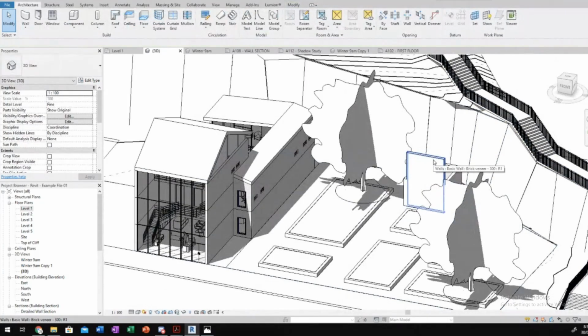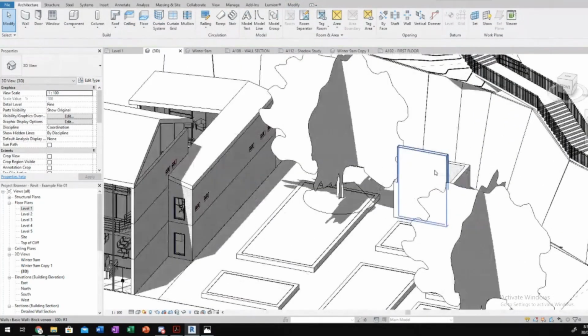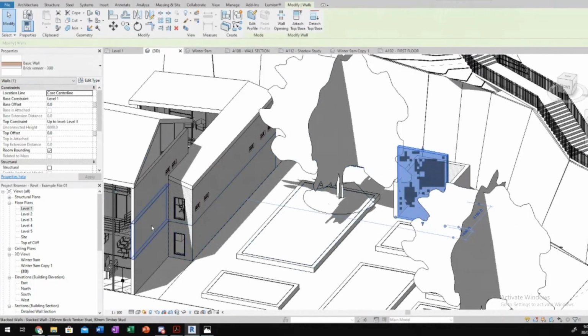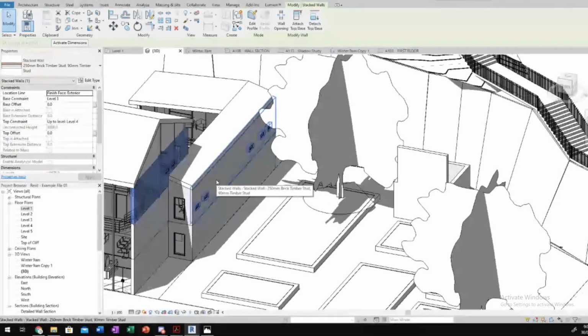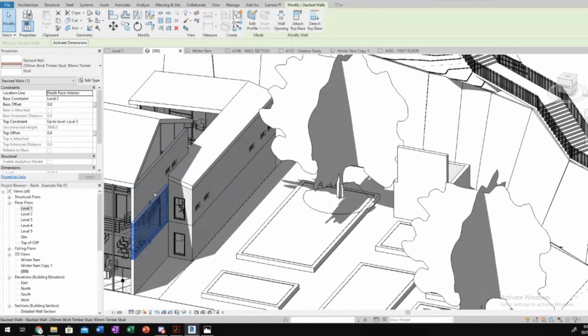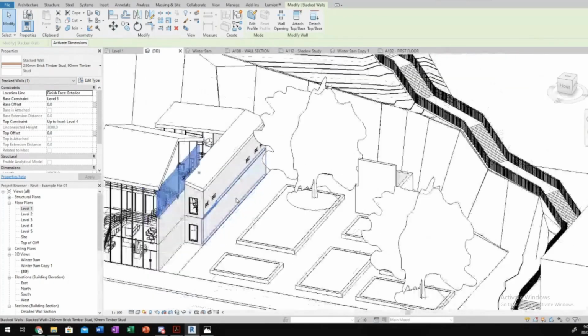However, my recommendation is, if you're ever working on a normal project or something, probably have your walls like this, where you've got a new wall for each level. It makes things a lot easier in terms of your drawing. Sometimes it might not cut properly. Revit sometimes has a lot of weird things. So yeah, I would recommend doing this.